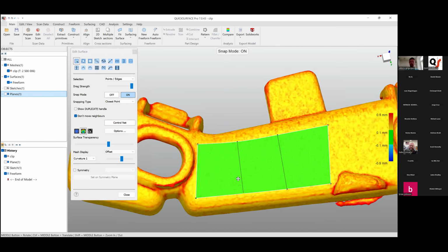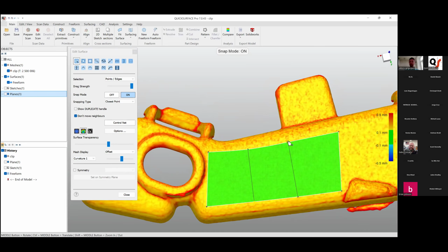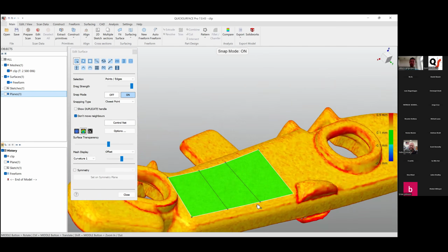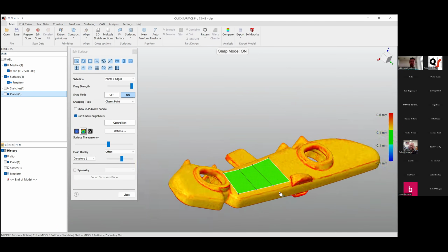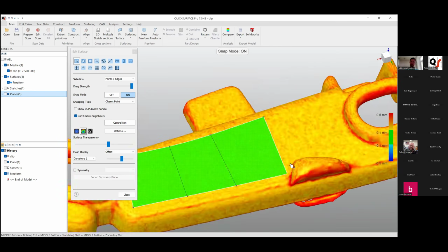And for easier operation, in some cases, we have a pretty cool shader. So this indicates more red regions in some corners or fillets, so we can estimate more properly how far we can stretch our freeform surface without going onto the actual fillet. Well, in this scan data, it's a bit rough, but still we can see these feature lines pretty okay.